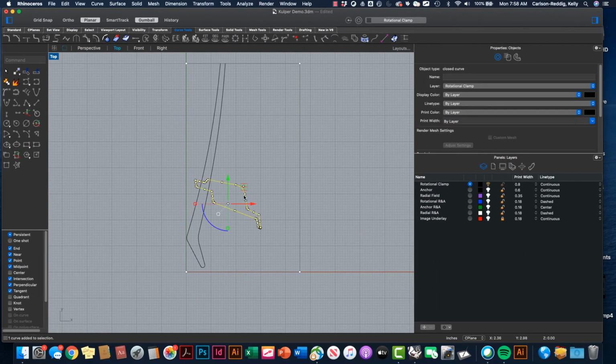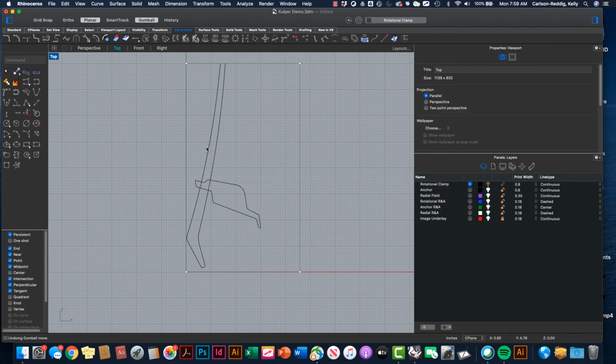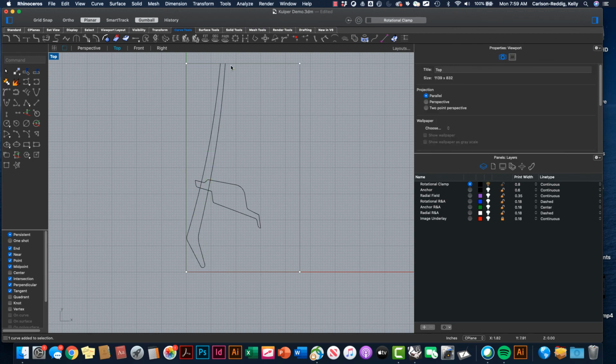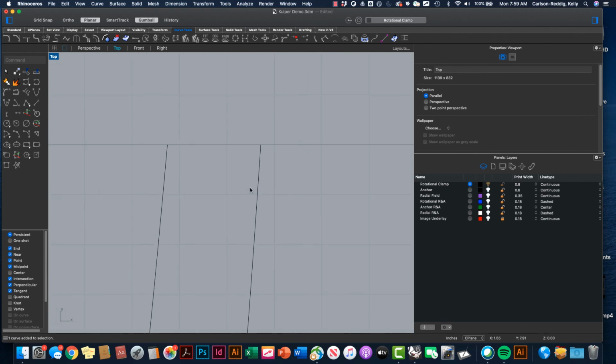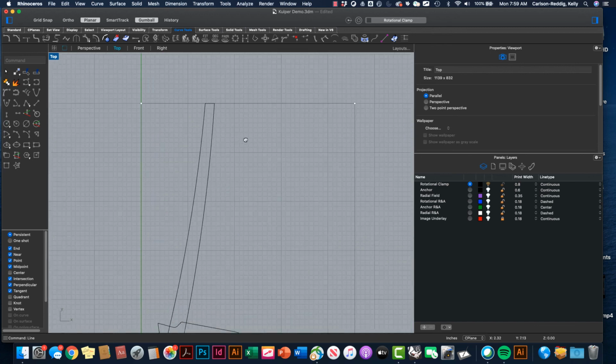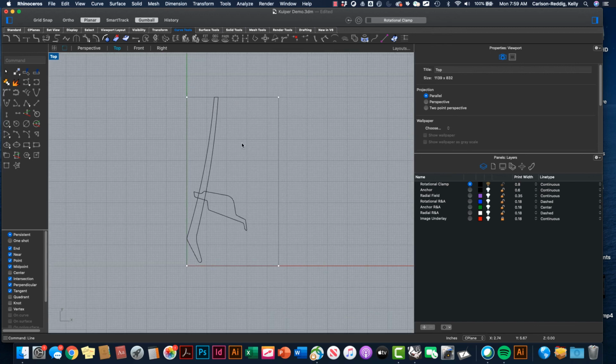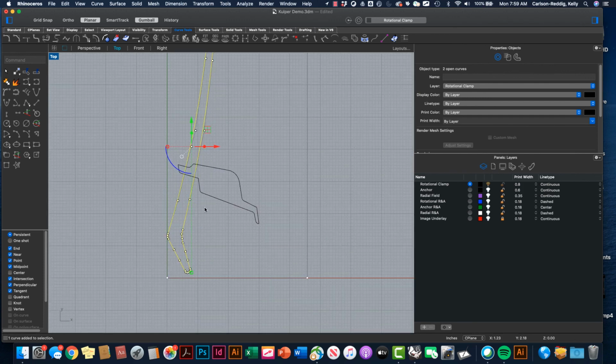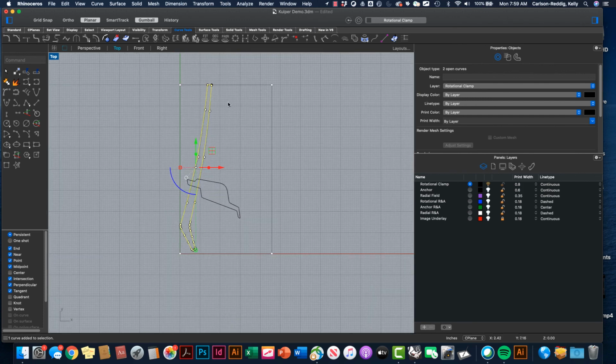Okay, now when I select this, I've got the whole thing, right? I'm not picking one curve at a time. So I want to do the same thing with this object. Now you'll recall I have two curves here, but I don't have anything at the end. So I'm going to go ahead and come up here and close this figure off with a line. And because I'm snapping to my objects, it snapped very cleanly to those lines. If I had a long line and I was trying to trim that, I could also use my trim command. Remember, I'm only getting that end, but if I drag right, everything I touch will be grabbed. So that looks like a closed figure. Let's go ahead and join it. All right, so now I've got one figure and another figure.